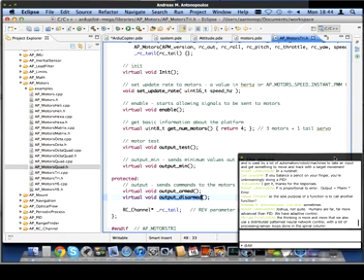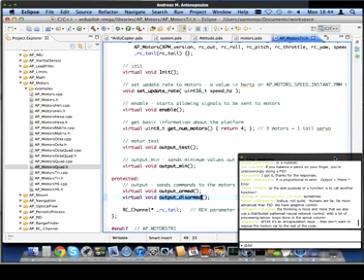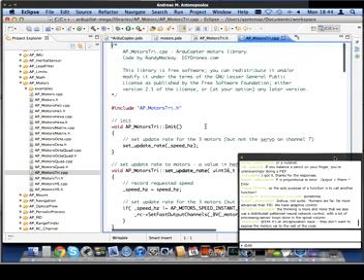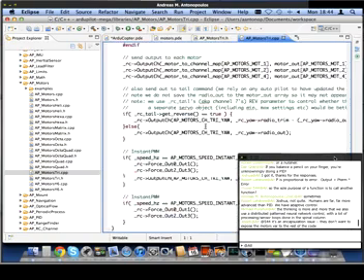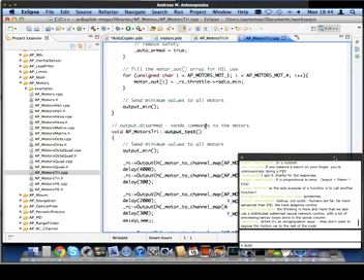And you might remember a moment ago when we were looking at the main ArduCopter code, it was calling a motors.output function. In fact, the motors.output function is implemented in AP motors.h. All it does is just check to see if the motors are armed or not. If it's armed, it in turn calls AP motors armed. And if it's not armed, then it calls AP motors disarmed.